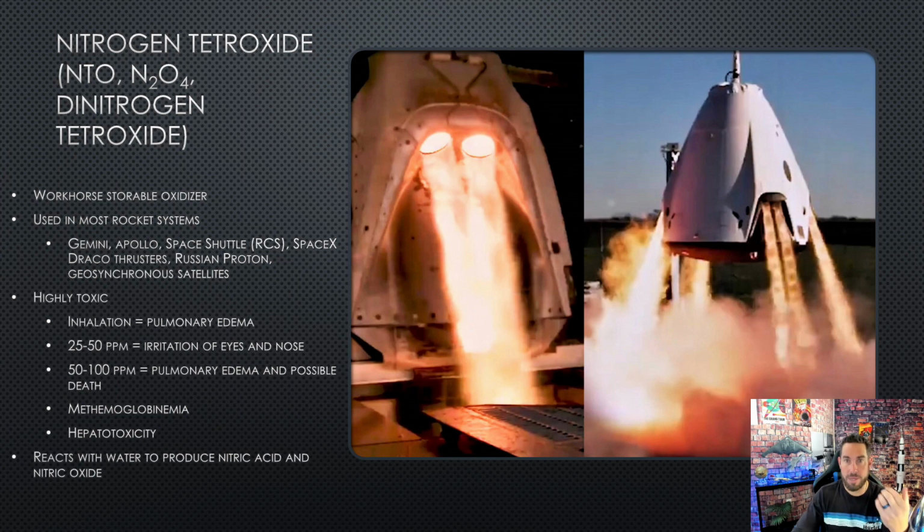There are fumes that can come off of it, so you have to be running oxygen masks. This is another reason why, I don't know if you remember the crew demo mission, with Bob and Doug, when they splashed back down, there were all these boats that encroached on the recovery area, and it was kind of a big deal. It's a huge safety issue for the boaters, because if they're exposed to this NTO and any fumes coming off of it, they could develop pulmonary edema, methemoglobinemia, hepatotoxicity. So anyway, just something to pay attention to.